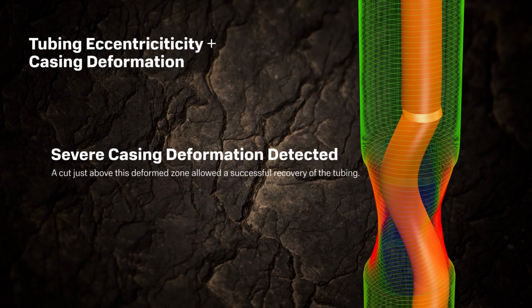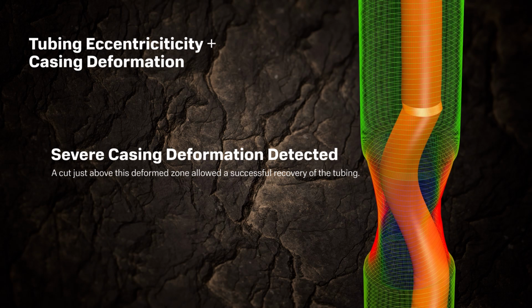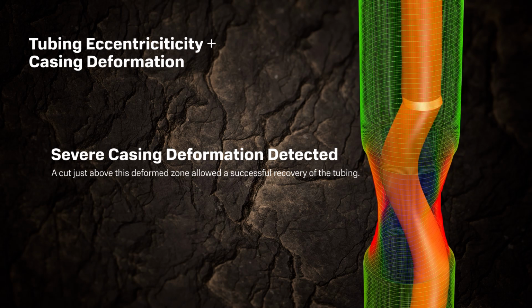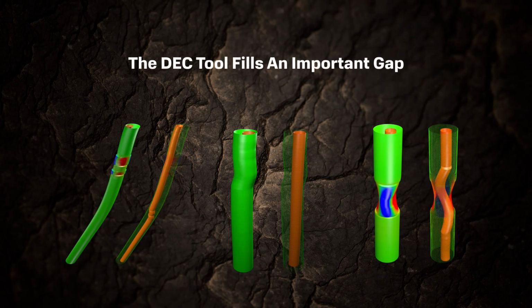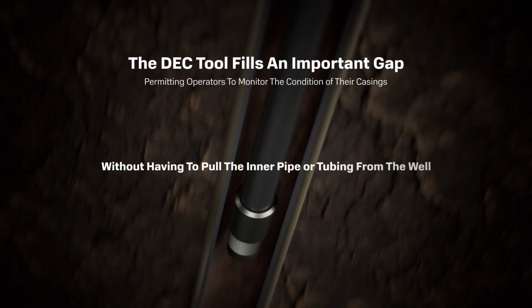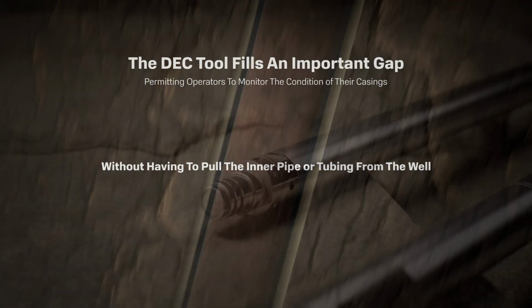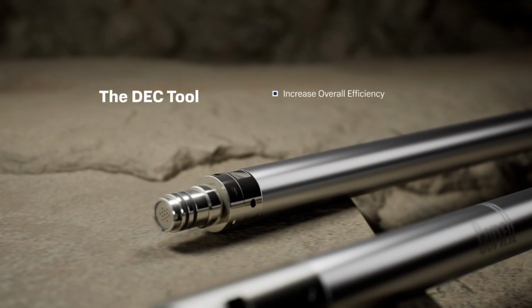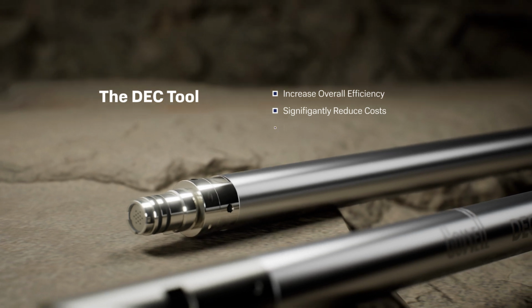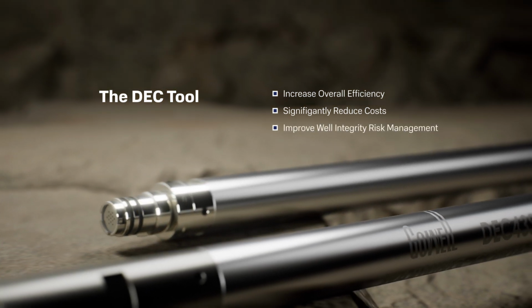A subsequent tubing cut just above this deformed zone allowed successful recovery of the tubing, and the workover continued with a revised program. The DEC tool fills an important gap in the pipe integrity diagnostics portfolio, permitting operators to monitor the condition of their casings without having to pull the inner pipe or tubing from the well. The DEC tool can assist in increasing overall efficiency and significantly reduce costs while improving well integrity risk management.